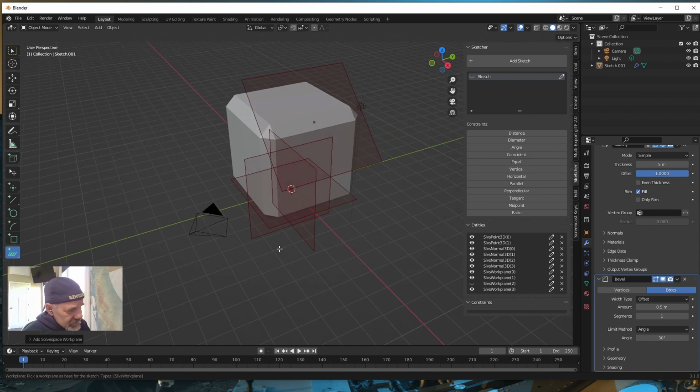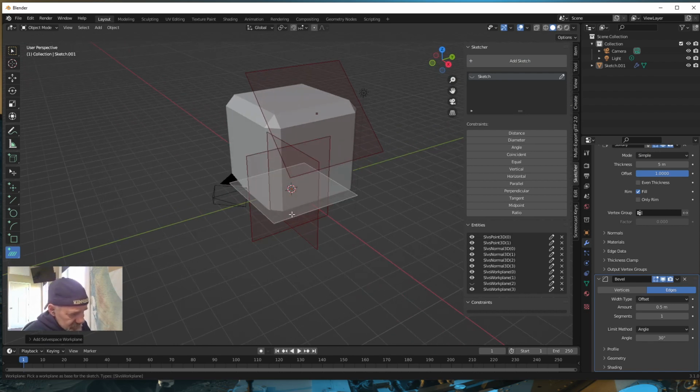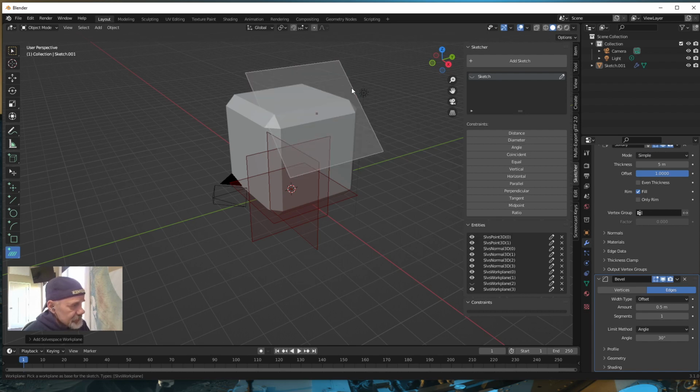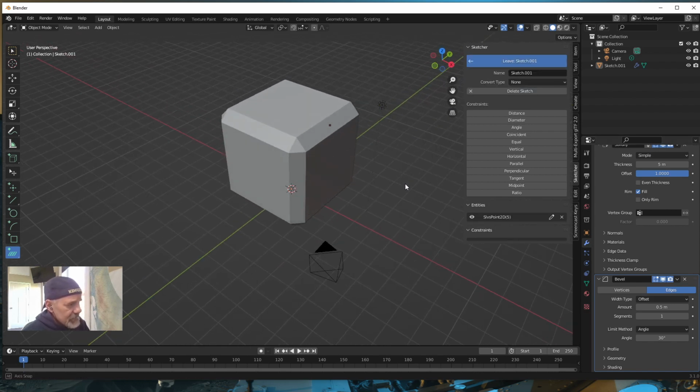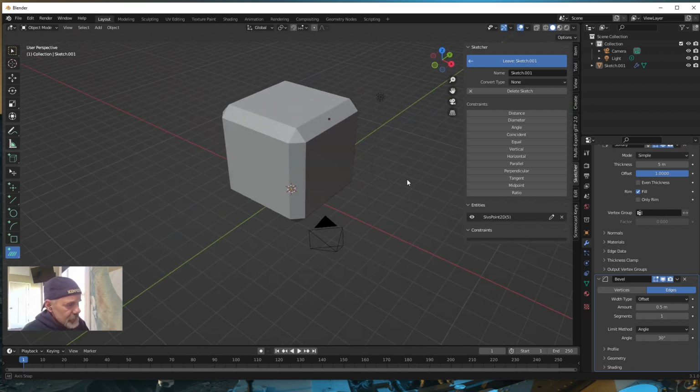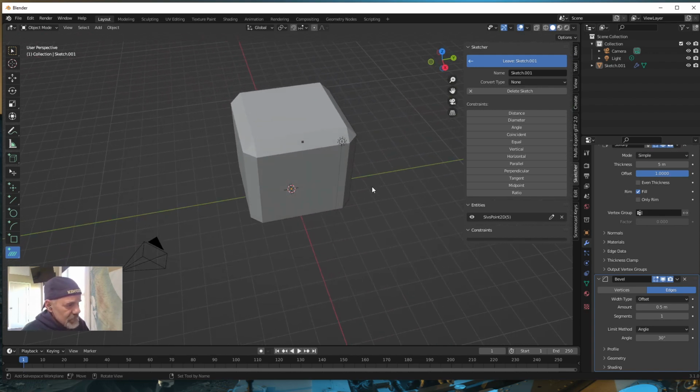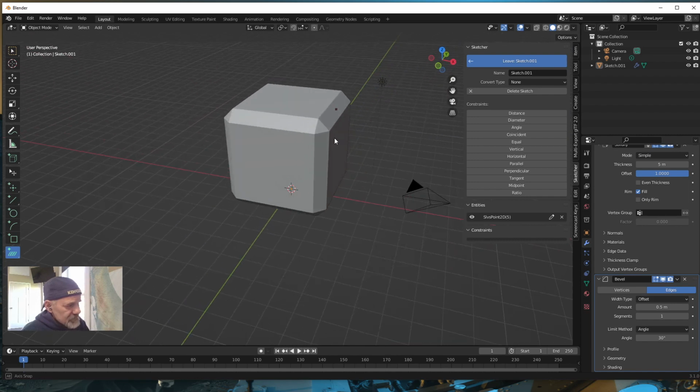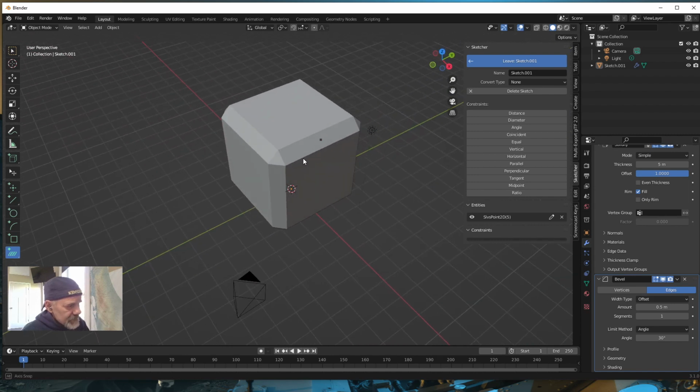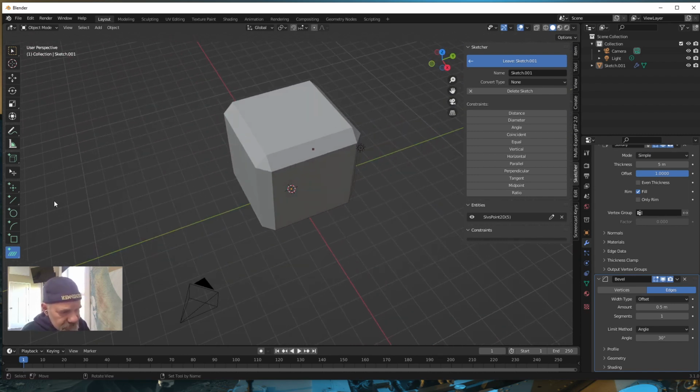And notice I get the default planes and our new plane. All right, so I'm going to select our new plane. Click. Now any object that I add or any sketch that I do is going to be oriented to this face. Okay, so what we're going to do is add a circle.